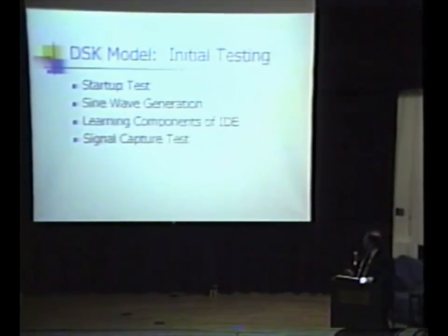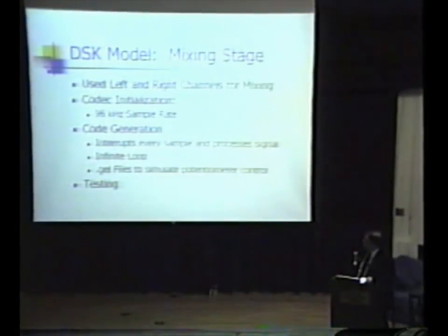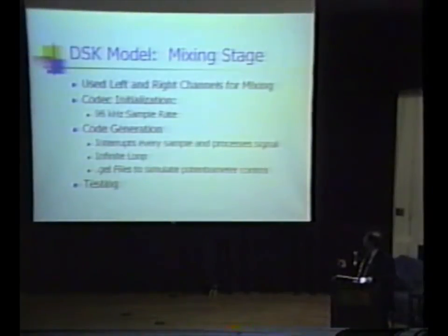The DSK model initially had a startup test, which was just to see if the board was working. I used sine wave generation to see if the board could output a signal, and to learn the components of the IDE. And I did a signal capture test so I could input a signal and output it, just to see if that worked. The first part was the mixing stage, which is the same model used in the VHDL model. It uses the left and right stereo channels for the mixing.